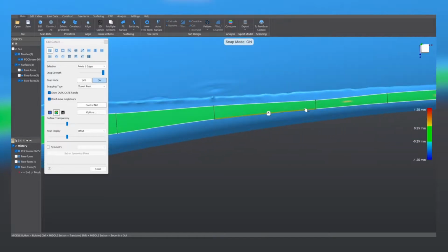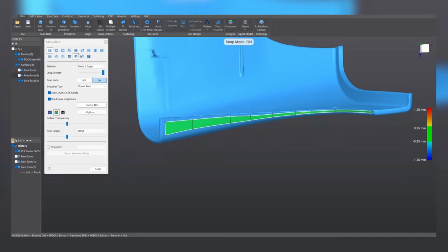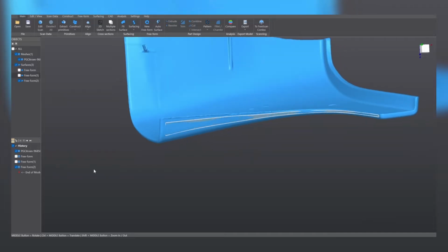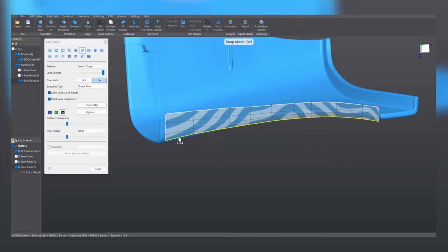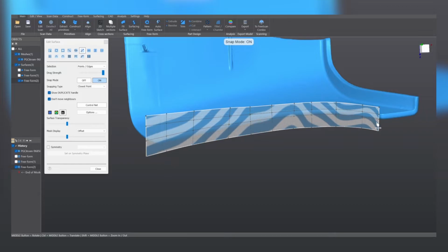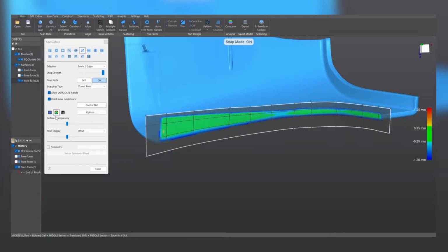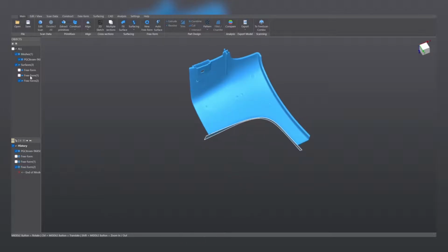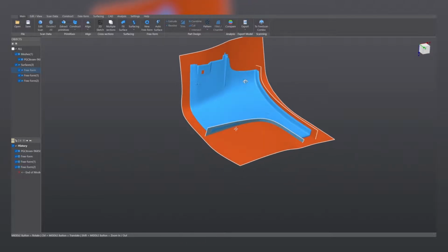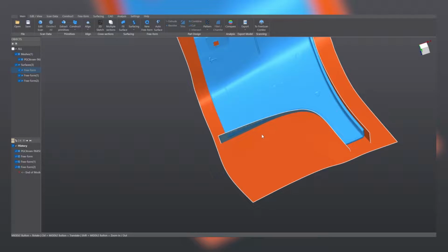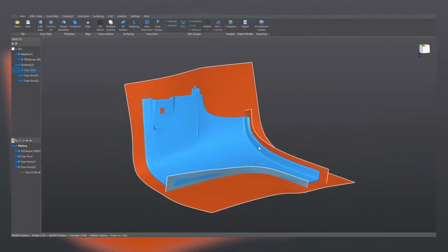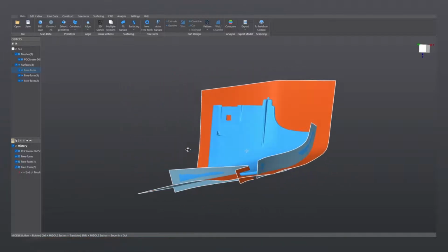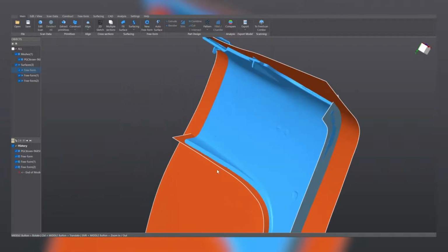Oh, actually that looks quite nice. And let's make it a little bit smoother to improve the surface quality. And I forgot again. Let's extrapolate it beyond the surface. Okay, that looks good. Click on close, and now observe the result. What we have here are freeforms that reproduce the outer shape of the mesh. However, we need to give it certain thickness, right?